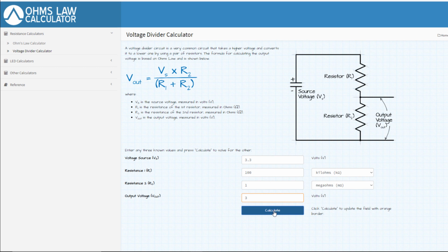So this is a very significant change: the voltage across my LDR changes from approximately 0.7 volts to 3 volts. This change is big enough to partition it in equal levels and then change the brightness of your screen accordingly.